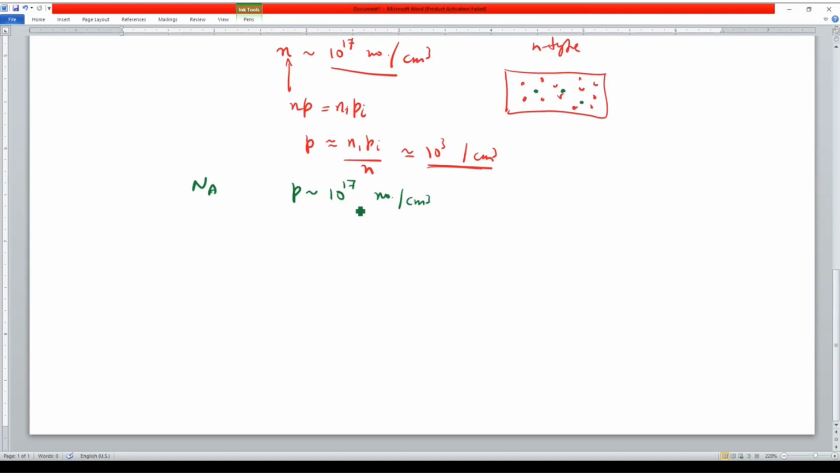So, not going into much detail, just defining the mobility of holes and the mobility of electrons. Okay, what is the formula for mobility? It is the drift velocity, not the plain velocity, over the applied electric field. And similarly, you have the drift velocity of holes over the applied electric field. So this is the mobility formula. Mobility is very important. Your mobility decides how fast or slow your system is.